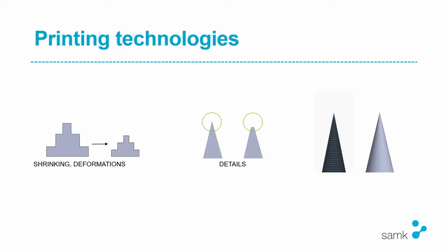And when talking about steel, when it's done with powder bed fusion, so DMLS, it can shrink plus minus 5% and more on the smaller holes or inner diameters for parts. With aluminium, shrinkage is plus minus 0.2 millimeters when the product is under 10 millimeters.